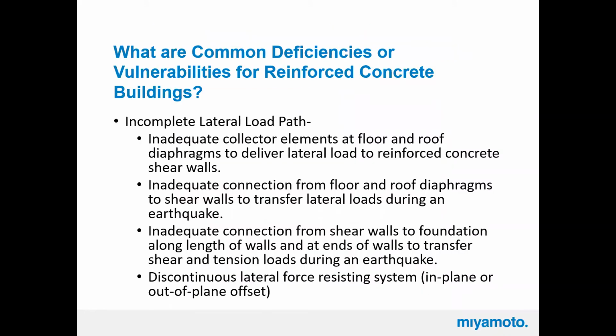A lot of things we see are really just incomplete load paths, or a lot of things not thought out about how the building works comprehensively. No collector elements to bring the load to the lateral force resisting elements, or inadequate collector elements or chords, that sort of thing. A lot of times the connections from the diaphragms to the walls or the lateral elements are inadequate. And then the same thing with the walls to the foundation.